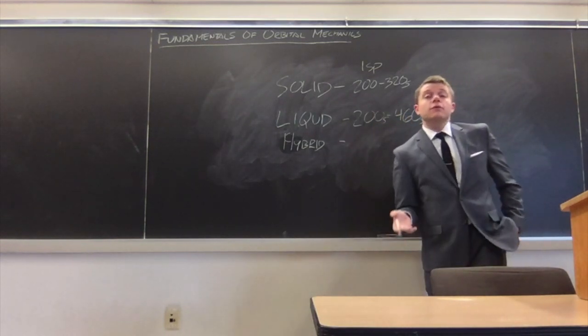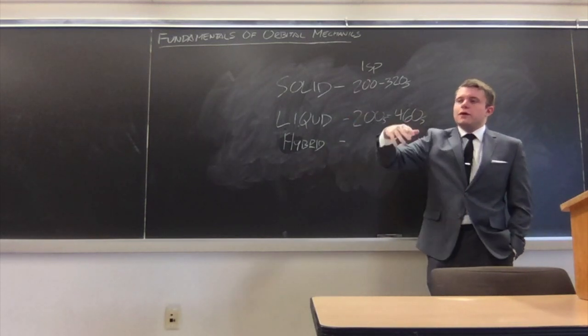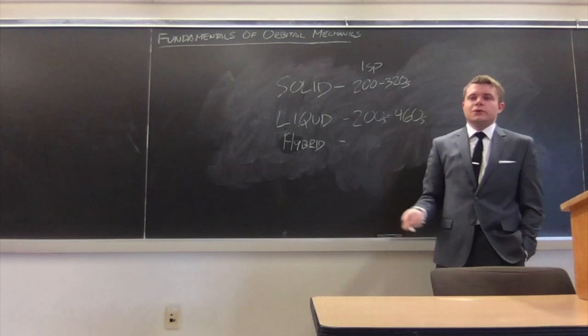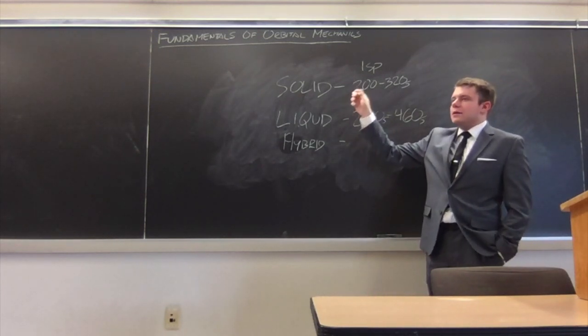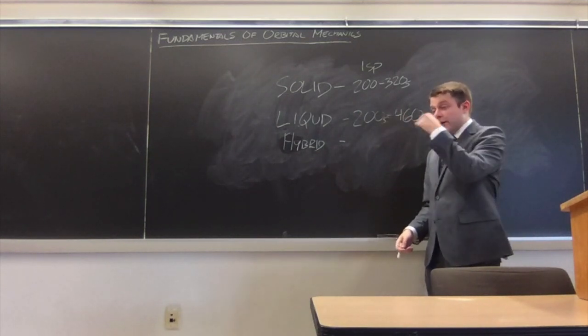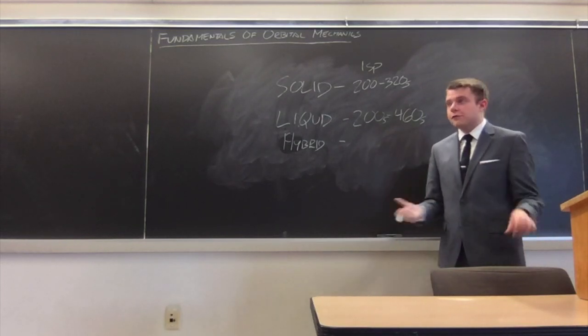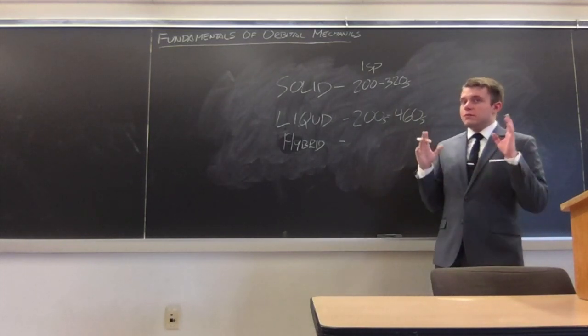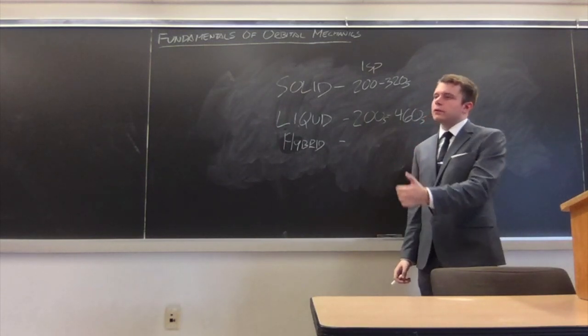And there are hybrid motors. Hybrid motors are quite interesting. Solid motors have the fuel and oxidizer, and we need both parts, as I didn't mention earlier but should be evident, embedded in a matrix. Then you have an igniter that sparks it up and allows the propellant to start burning. It's a self-sustaining process. You can't shut it off. And that's both good and bad. It means you can make solid motors very, very reliable, but you cannot control how much thrust they produce.